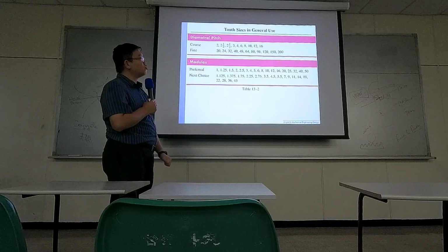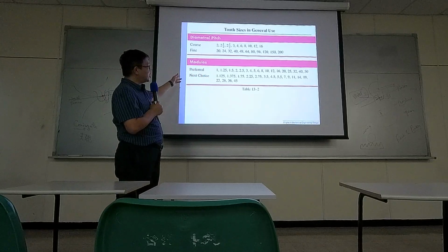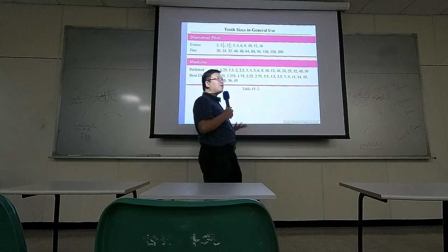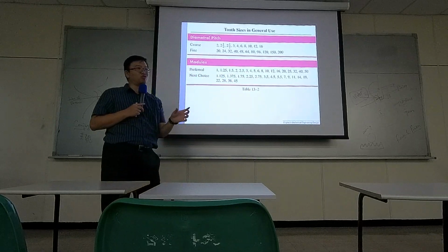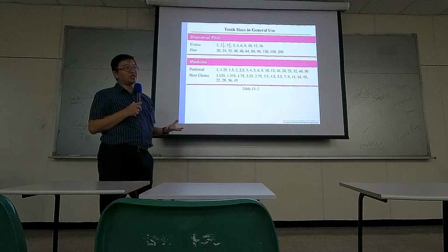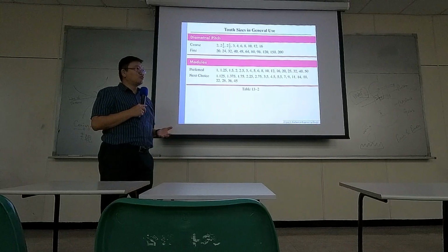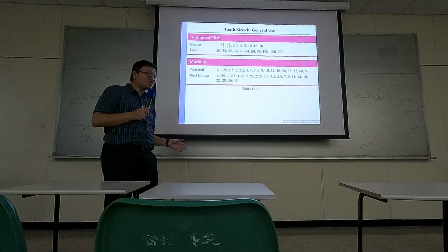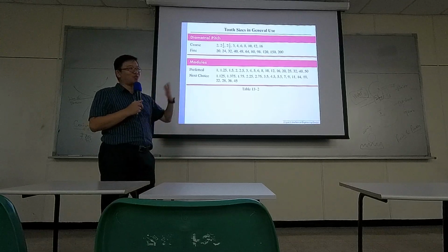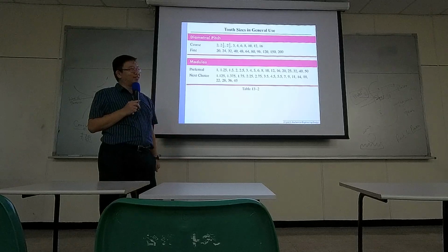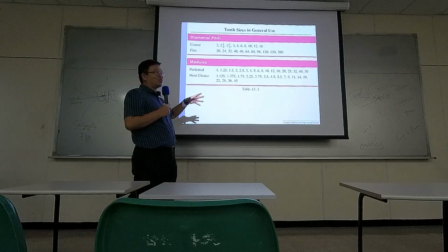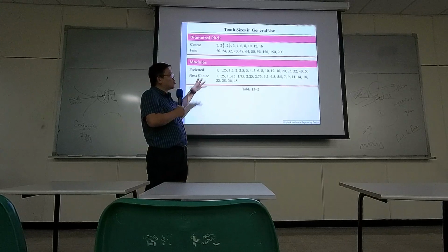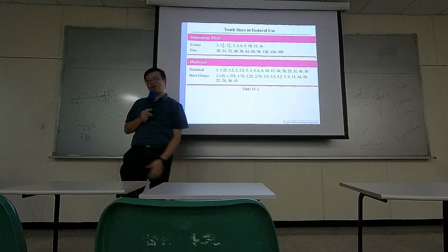If one day you want to design a gear with a unique module, for example 9, maybe the manufacturer doesn't have the tool to make it. So what do you do in that case? You probably need to manufacture the cutting tool first, maybe by CNC machine or something else. So it's like a customized profile of the gear. So designers tend not to do that because it's more troublesome.